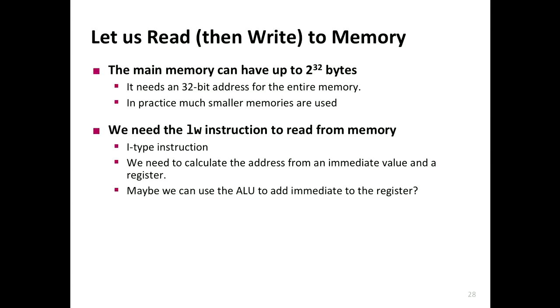But now, when you want to read from the memory, you need to implement the load word instruction, right? Till now we saw how to implement R-type instructions, and now we are going to see how we can incorporate an I-type instruction, because load word is an I-type instruction, and also we need to calculate. So let me write this down.